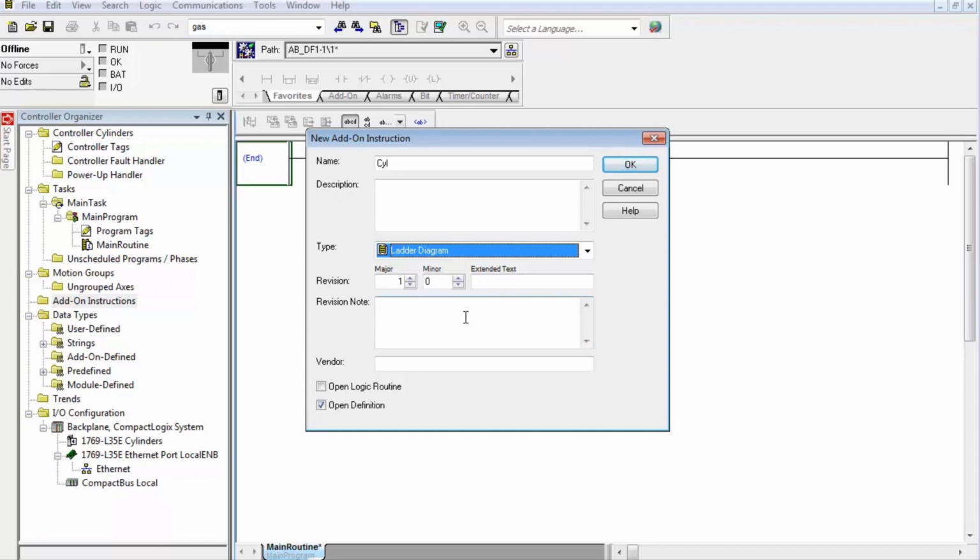So remember that you're creating a class of objects that's going to be in this group down here. It's an add-on instruction, but you're going to have add-on defined as well. And these are classes of objects. These aren't instances. Think of an add-on instruction as having a program in it, and the program has a major and a minor rev level. As you import, export, and reuse this add-on instruction, it is important that you keep track of the major and the minor rev level, because let's say you created 10 projects over a couple years using your add-on instruction.